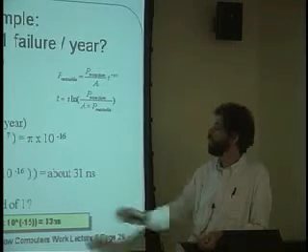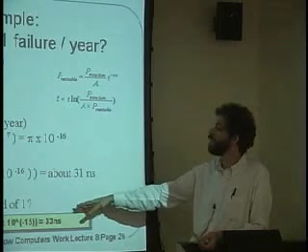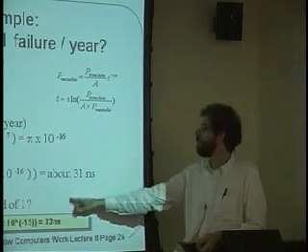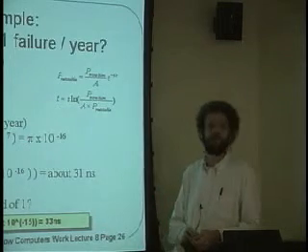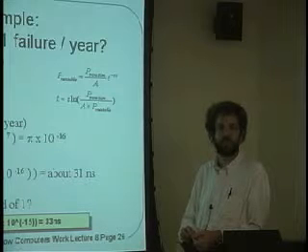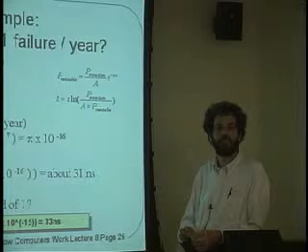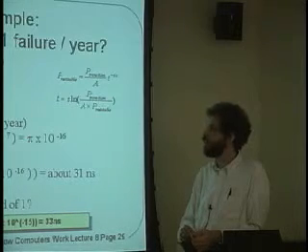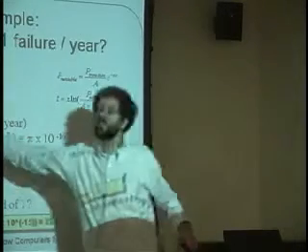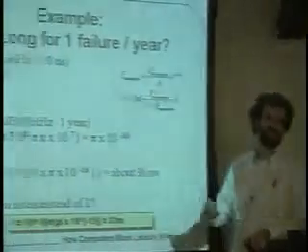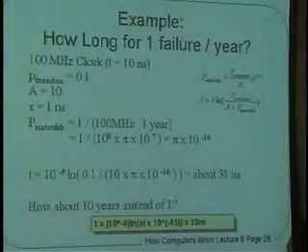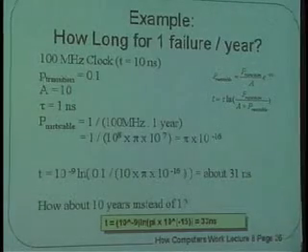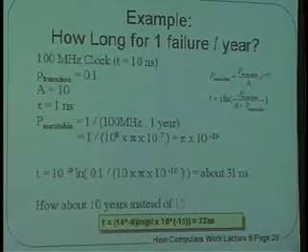And so if we want to decrease the probability by a factor of 10, it turns out we only need to wait 33 nanoseconds instead of 31. How fixed is the value of tau? Because that has a tremendous effect on the system. That's absolutely right. So if this was 0.1, then this might become much less than that. It would be 3 point something nanoseconds as opposed to 33. But these are sort of typical values that are out there. Yep. And A is pretty much fixed too.